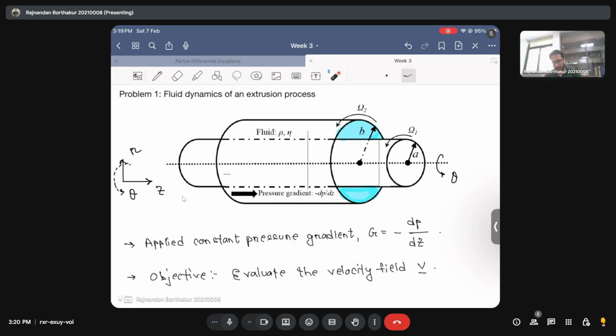Okay, so these black objects, as you can see here, in this case in the shape of a cylinder, are typically known as dies. The reason why you insert the molten material in between these dies is that you want the molten material to get a particular shape. For instance, if you want to get a ring, what you do is prepare two dies which are concentric cylinders and then insert the material in between the two dies.